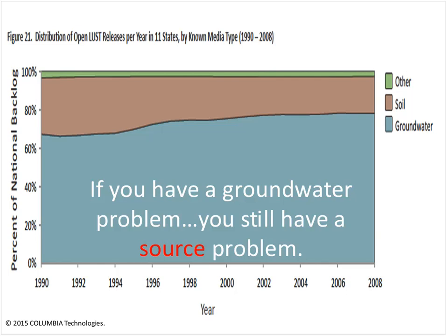The other way of looking at this storage and transport issue is if you still have a low-level groundwater problem on your site, then you still have some sort of residual source. So there's a storage, secondary or primary storage problem that's causing your recurring groundwater levels. Pretty clear that if you remove the source, the groundwater is going to clear out those soils, and we're not going to have any further contamination. But if you've still got back diffusion going on, then there is a source somewhere that's causing that issue.